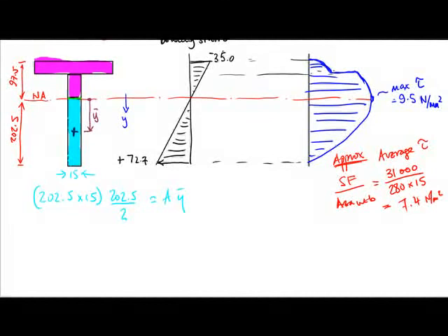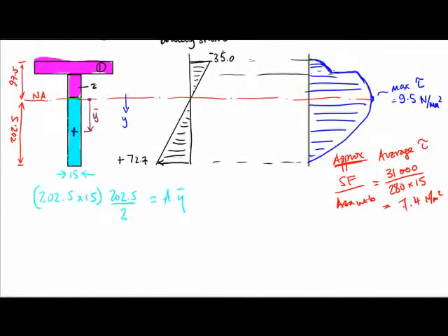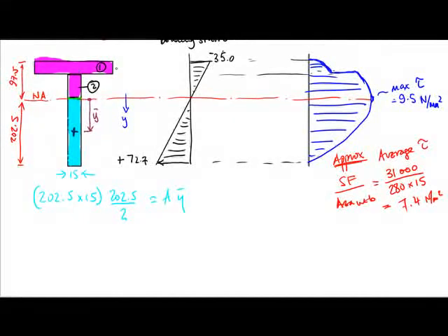Now if we did the Ay-bar in the purple, then we should get exactly the same answer, but it is a little bit more involved because there are now two blocks to it. I'll call the top one 1, and I'll call this number 2. So let's do the Ay-bar of the top block, so it's got the centroid there and the centroid there.